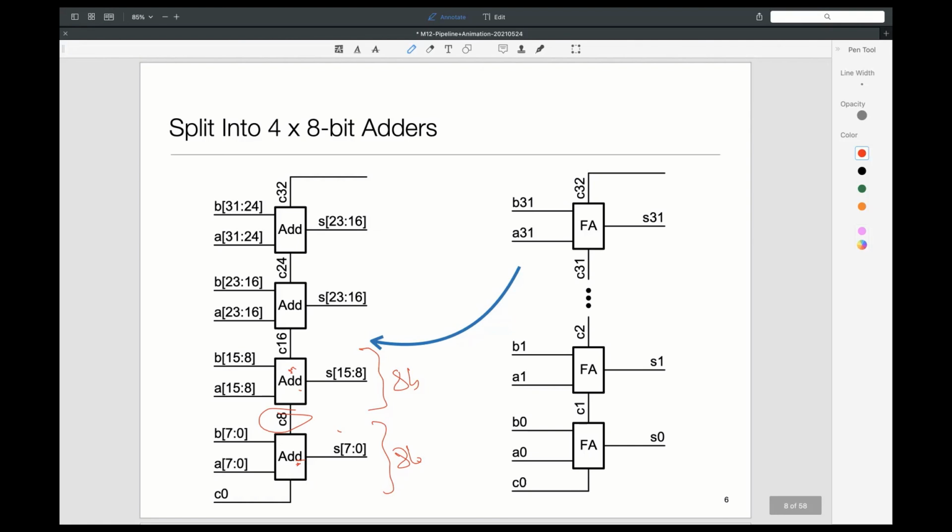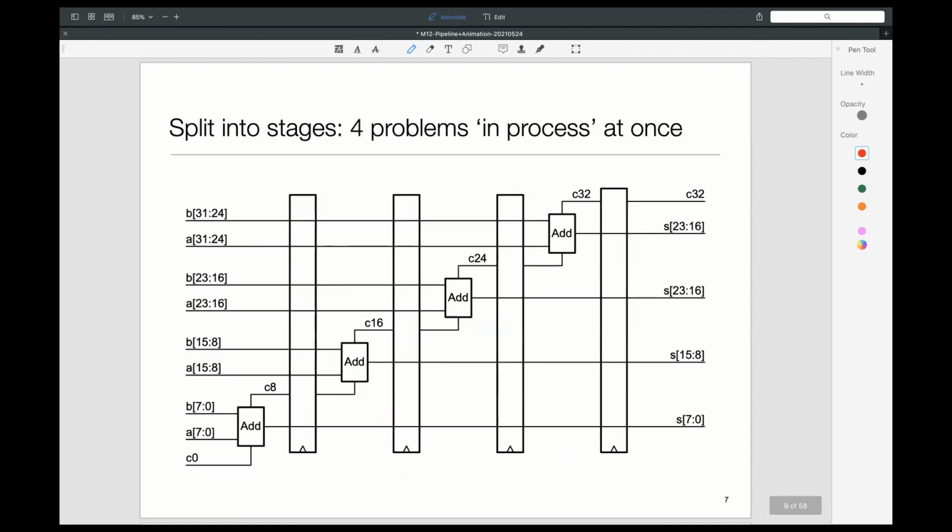So what is our analog? It's the clock tick. Think of the clock tick as when the work moves, when the product, the data, moves from one combinational hardware to the next combinational hardware, where the next computation will be done. So the clock tick is registers. This is how our circuit is going to look. This is what is called the pipeline circuit. These are all registers, as you can see. This is the clock. And these are 32-bit registers.